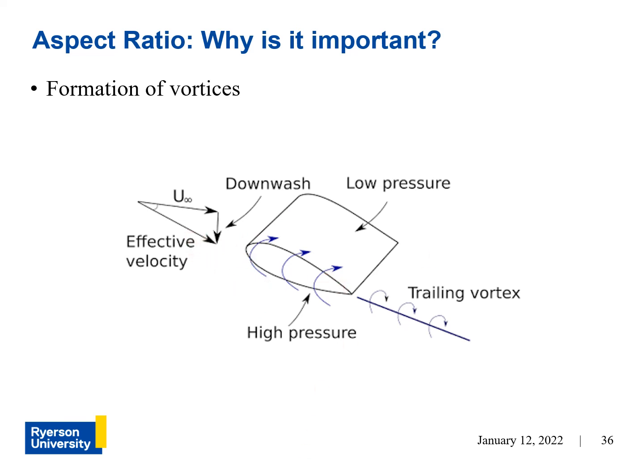And again, remember from before, angle of attack affects the lift generated by the airfoil. And if the effective angle of attack is lowered, as seen by the airfoil, because of this downwash, the lift generated would be lower than what it would have been.